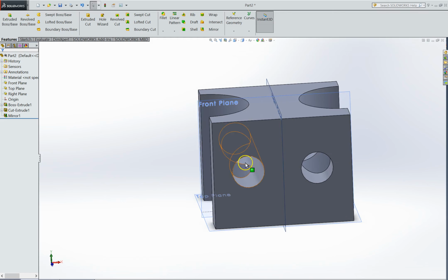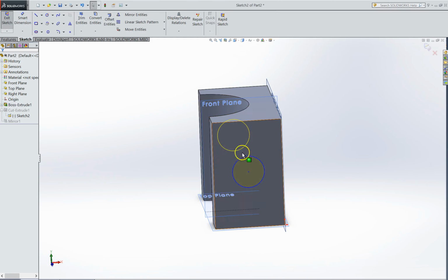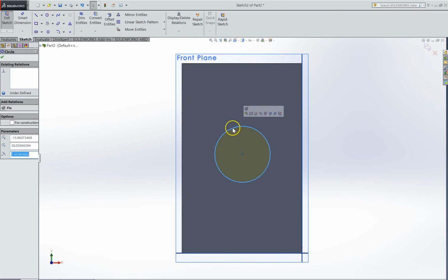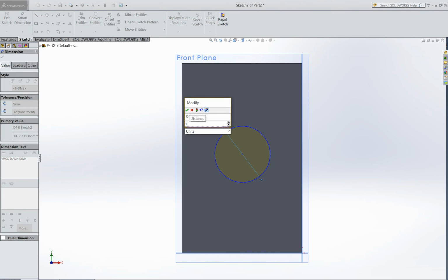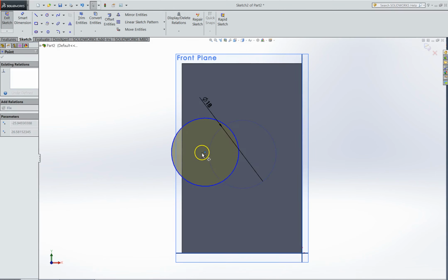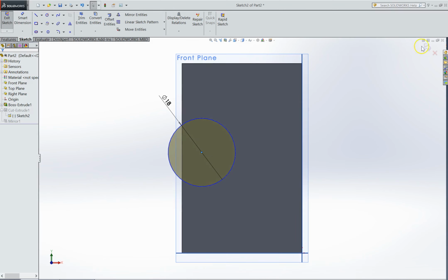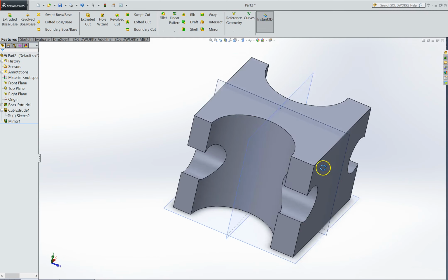This means that everything I do initially, on the left-hand side, will be mirrored across that midplane. So if, for example, I go into that cut, into that sketch, and say I change the size of it, let's have a look, line that up. There, look in the sketch, smart dimensions, I'm going to change that size from 14 to 18mm, and I'm actually going to move it maybe along a bit to this edge here. Okay, so I've made that change, and as you can see, that change has instantly taken effect over our mirror plane.